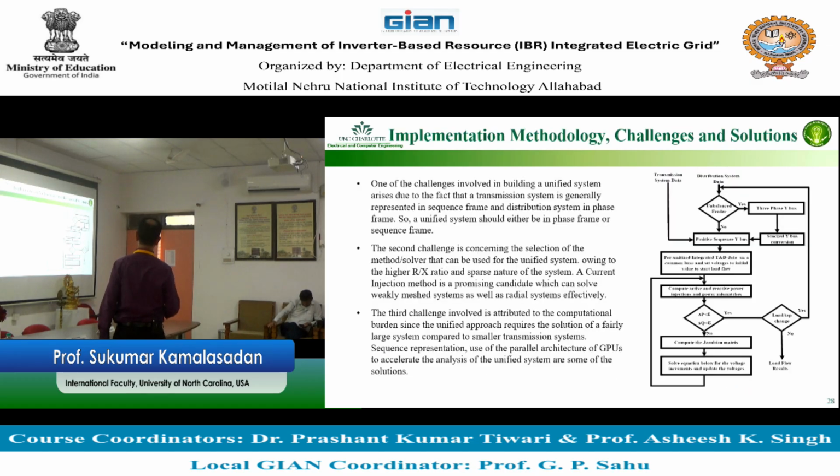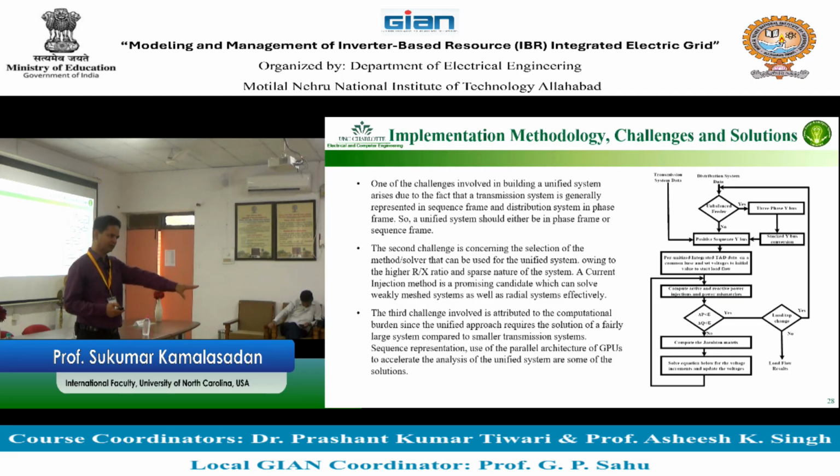And once you have that, you can run the unified power flow with a positive sequence Y bus, stacked Y bus approach. Oh, by the way, this will be run in positive sequence mode because the transmission system is positive sequence, and then you'll be running the positive sequence for the distribution system.